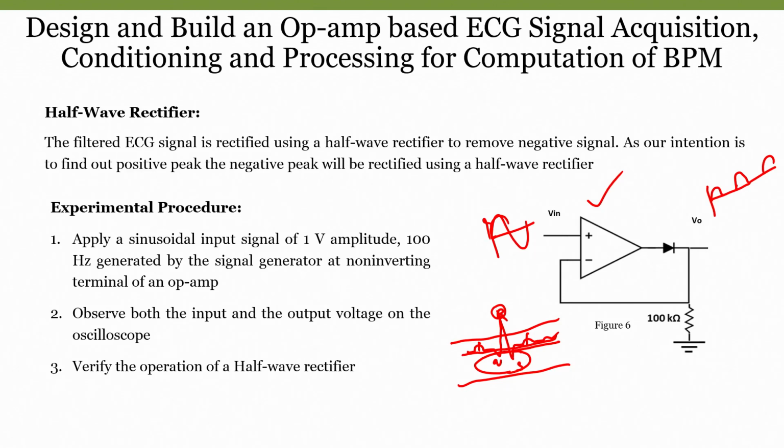That is the reason. As we already know, the QRS peak is very tall, having a very high amplitude compared to other peaks. If we can detect this particular peak, our problem is solved. In order to detect that, we are using a capacitor which stores the complete highest voltage, but how do we create a threshold? If I can create a threshold and compare the output signal with the input signal, then whichever is the highest, I can decide it.